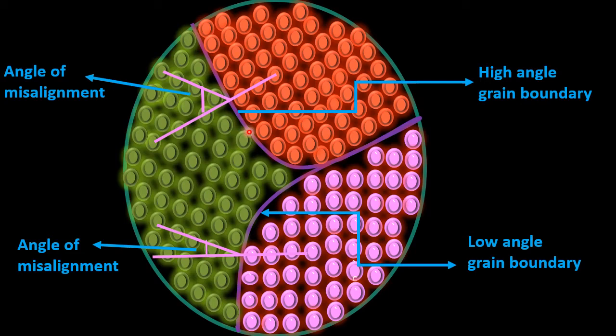This is just because in the interior of the crystals, the atoms have more nearest neighbors and they have more extensive bonding as compared to the atoms which are at the boundaries. These have less extensive bonding, so because of this, these are at higher energies as compared to the interior atoms. So just is the case with these grains. These grain boundaries are at higher energies as compared to the interior of the crystal structures.